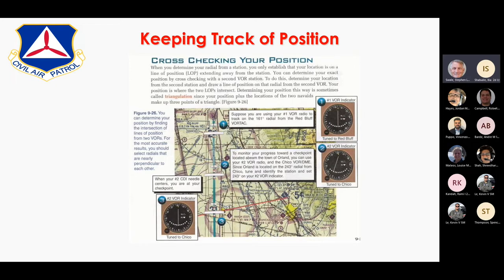So this is a skill that, if you are not up on your sectionals, I suggest you really study them again and memorize all the symbols. Remember that you can see the legend for those symbols on the edge of the sectional. If you have ForeFlight, you can look up the legends in the documents section of ForeFlight if you forget what something means.